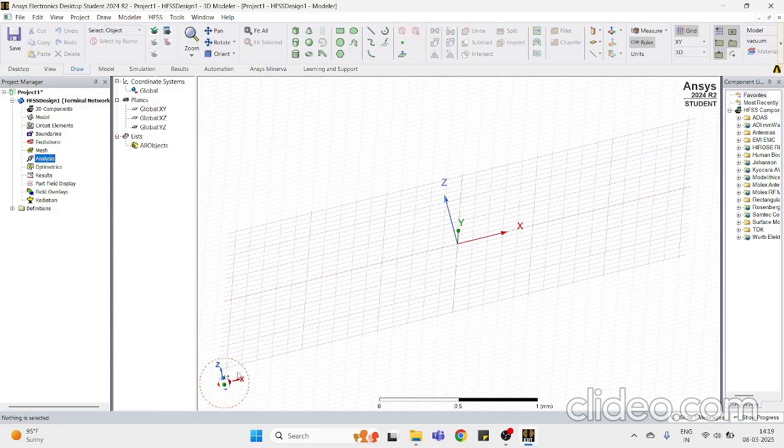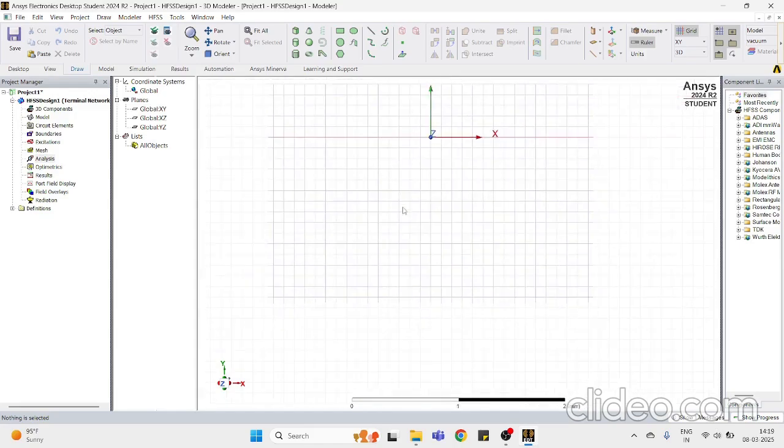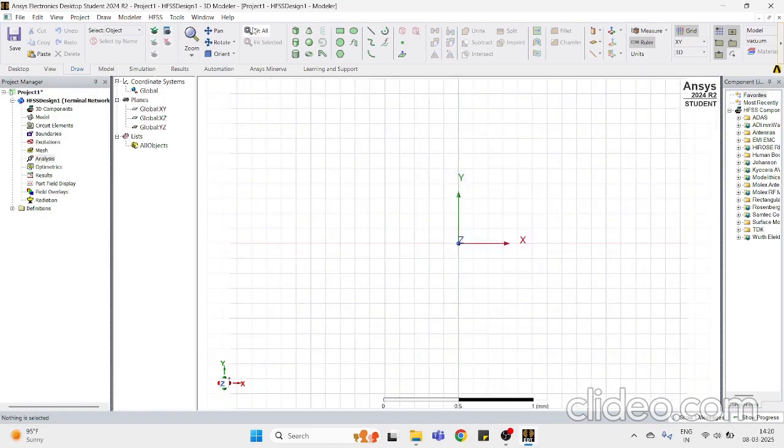So coming to the very first experiment, microstrip line. Talking about microstrip line, the point of performing the experiment is to check how good that microstrip line is transmitting the power that is pumped in. So a microstrip line has ports at two ends, and whatever power you pump in at one port should completely be transmitted at the other end. That is the point of a microstrip line. But here, since we are performing practical simulations, you'll see that not everything gets transmitted and there are some reflections.